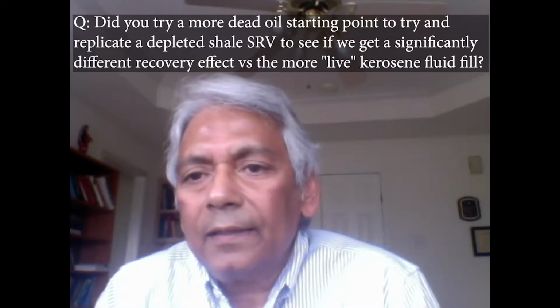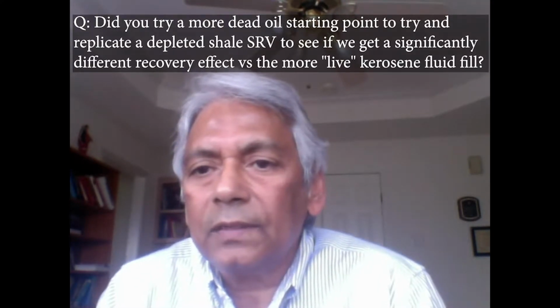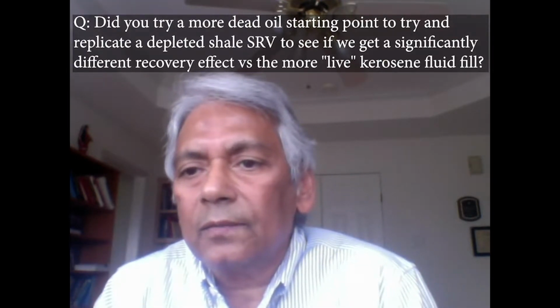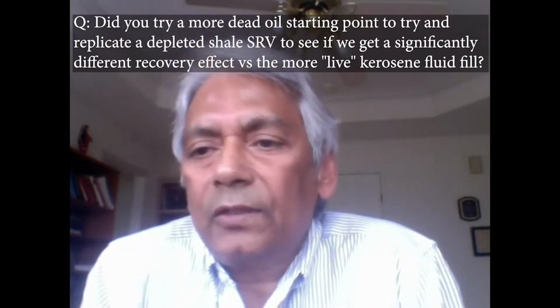Did you try a more dead oil starting point to try and replicate a depleted shale SRV to see if you get a significantly different recovery versus more live kerosene oil? Actually, we have been doing mostly with kerosene, but certainly we need to try it with other oils. So we would love to work with other companies who give us some of the field oils and the field rocks that are of your interest, and we would love to try them out both in dead and live conditions and see what effect it has.